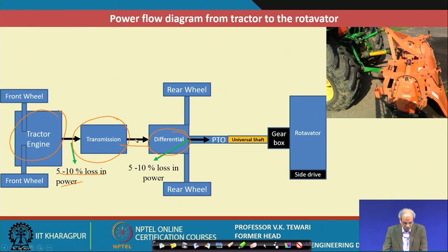and where its importance lies, and how the power from this goes to the two rear wheels. Now, we know that in the transmission, power to the PTO goes from the lay shaft or the counter shaft. This is directly connected to the PTO here. In some of the tractors you will find ground PTO and engine PTO. Not many tractors have this, but in some of the tractors you will find it like this. So, this is how the PTO is available to you.